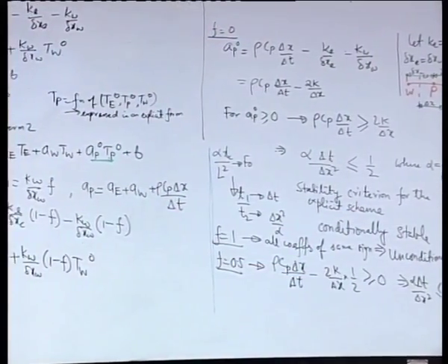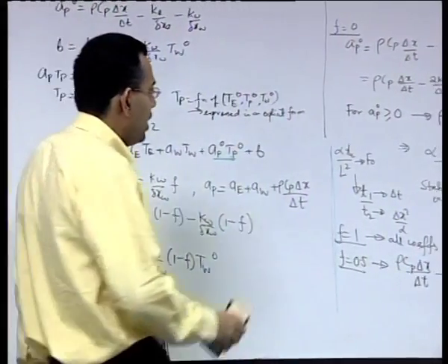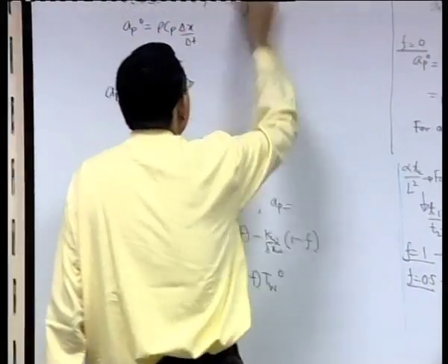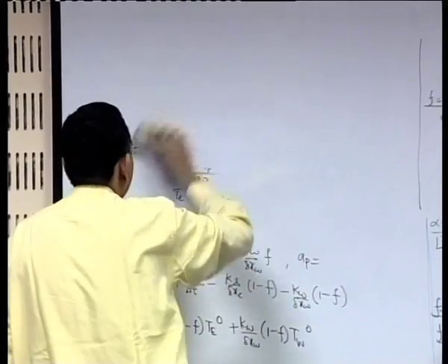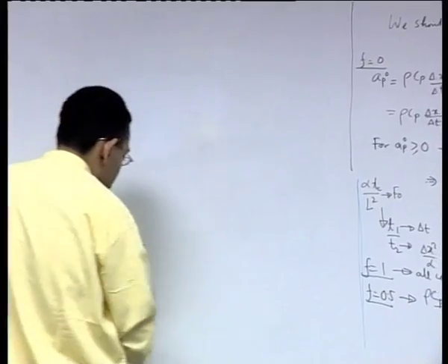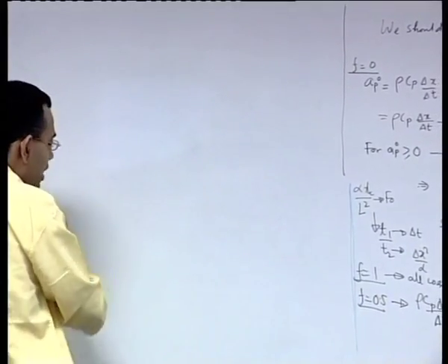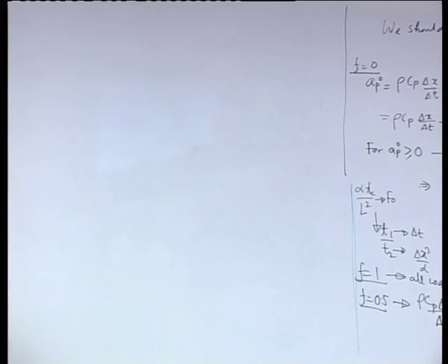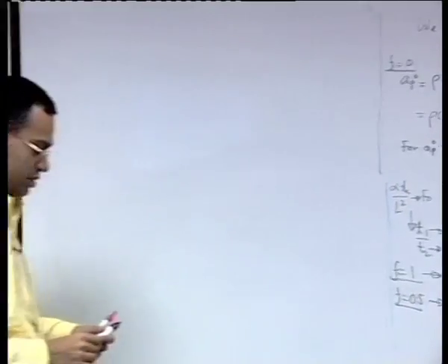Now, so far we have discussed the consequences of the discretization scheme from a finite volume discretization angle. Now we would also like to draw a parallel analogy with the finite difference discretization of the time and the space coordinates.